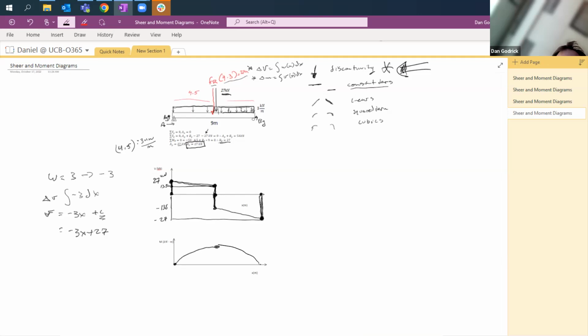And when we have our maximum moment, the one thing that we have to be careful about is that our equations are a little different for when we're before that discontinuity, that applied load, and after it. So we just got to be careful. But we can see that in this particular case, there's a great deal of symmetry. We have some positive area and we have some negative area.